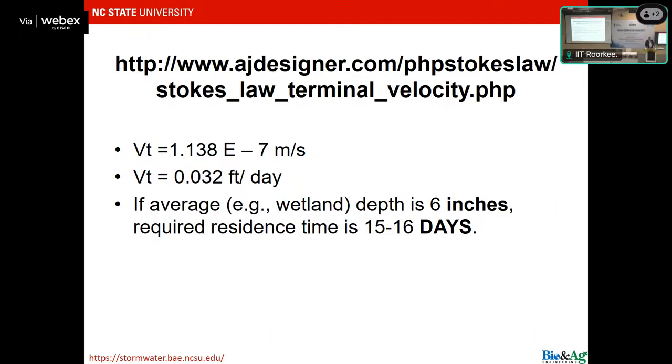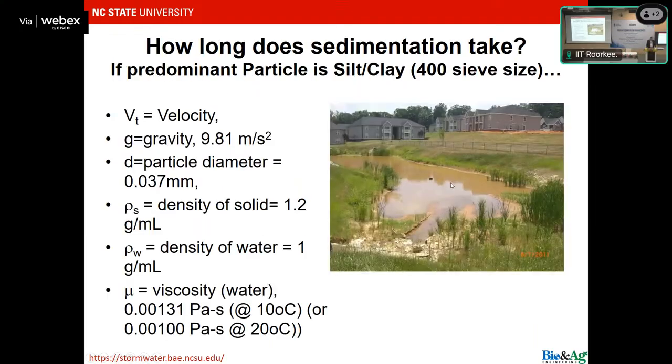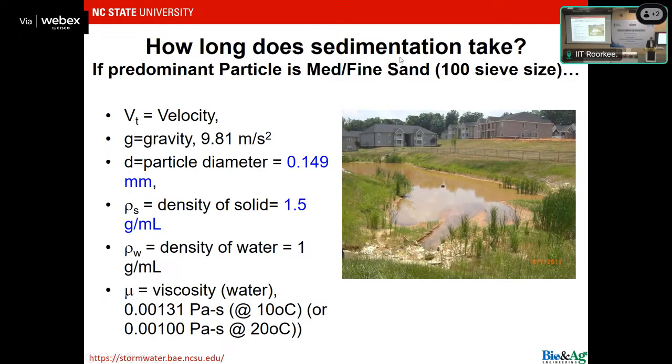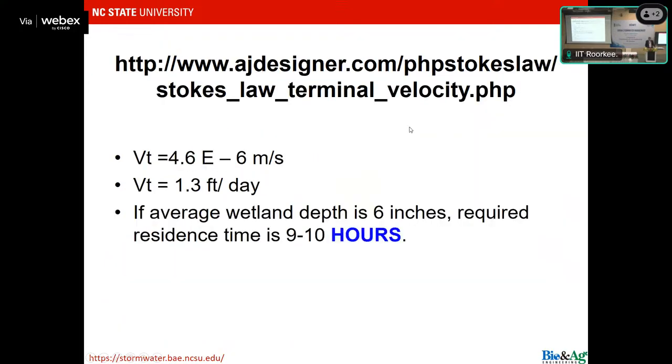It is not good if you have clays, but it is good if you have sands. All right. So the exact same calculation, this time we're running it for sand particles, and instead of needing weeks, 2 weeks, thank you for that, by the way, instead of needing 2 weeks for the particles to fall out, you just need hours. You measure it in hours. So it's in your interest. I mean, it is what it is. You can't change the soil you've got, right? But it's in your interest to have coarser grain particles for sedimentation to work.